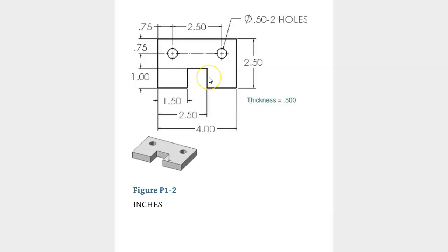the notch in the center, we'll talk about contours and regions. We'll start that conversation. We're not going to get too far into it, but contours and regions versus going through and doing a trim. So the geometry is not overly complicated. We'll go with a rectangle and then the two circles. And rather than defining the circle positions independently, we'll use a horizontal relation.